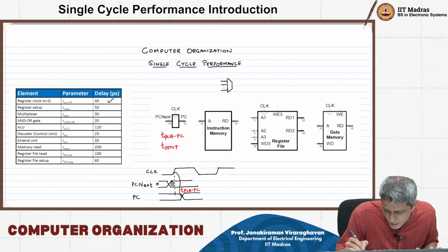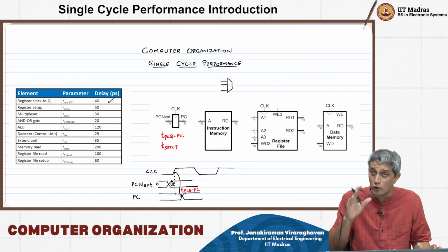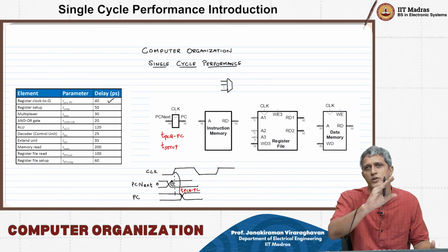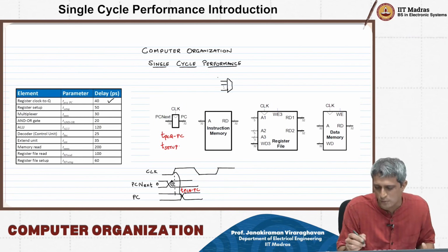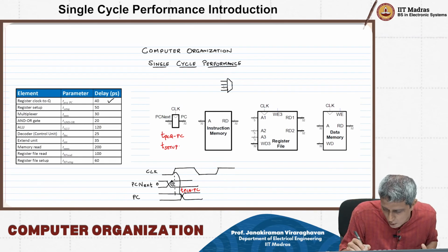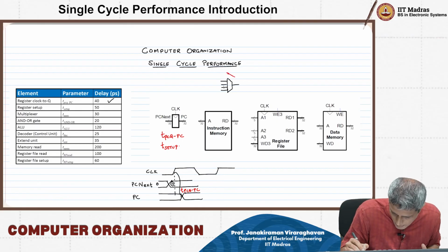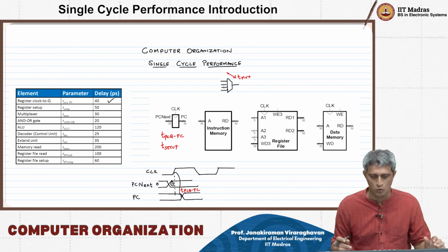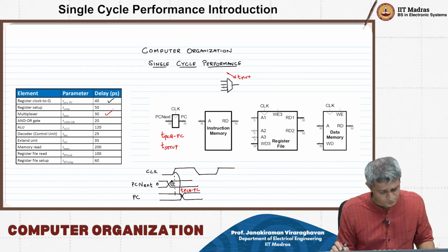This could be, it's not a very large mux, so it's just about 2 input. Of course each input could be 32 bits, so it could be 32 muxes, 2:1 muxes in parallel, right, or 4:1 muxes, right. So we are talking about some small mux like that, and we are talking about T mux, basically this delay, the delay for the input to go to the output, and that's what we are talking about here, right.